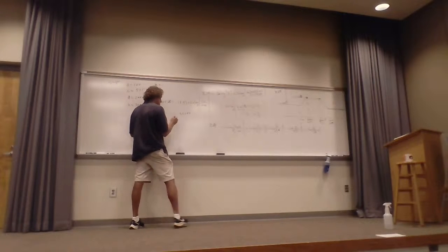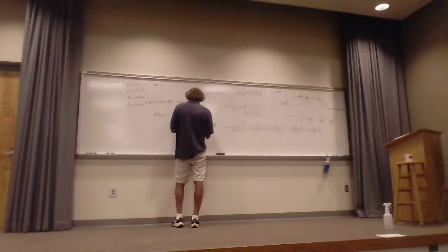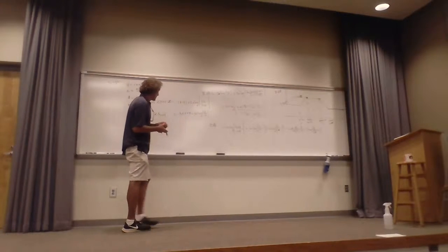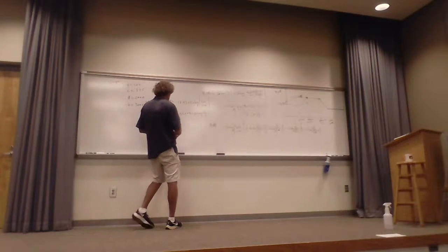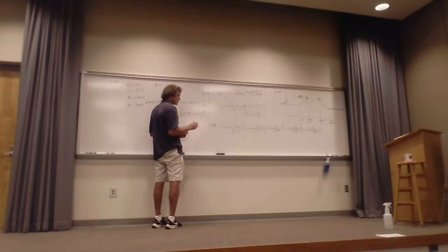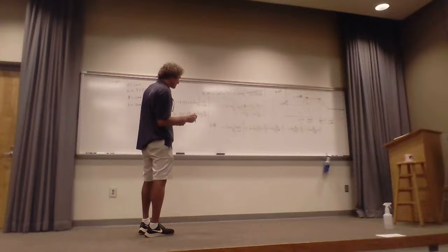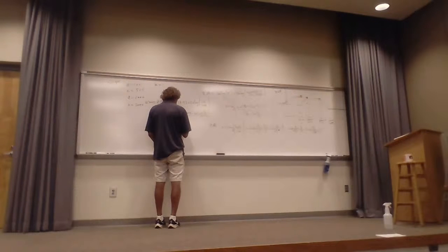The way we get that is we take this and then subtract minus 20 times the log of the upper frequency, which is 3,000, over the lower, which is 2,000. Now what do you get there? Your final answer is going to be negative 7.05 dB. This plus this? Yes. It should be greater in magnitude, a more negative number. Goes down. Minus 7.05.